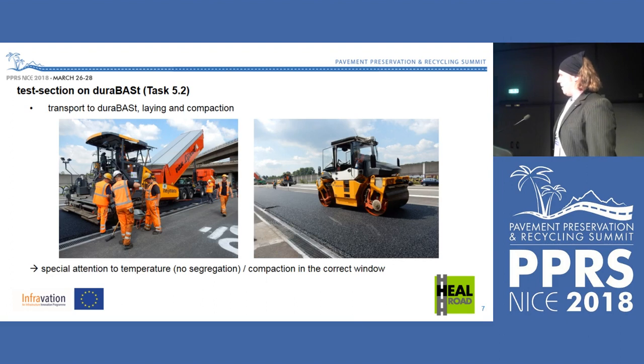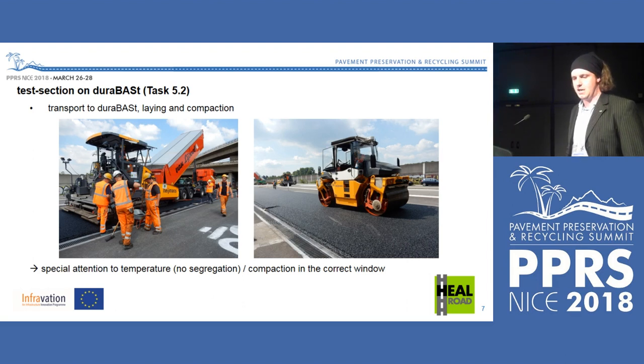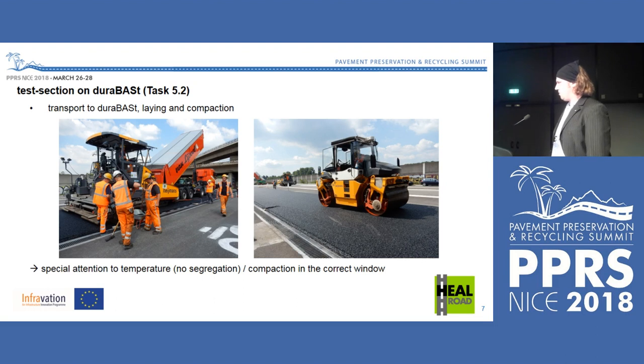The asphalt material was mixed in the Netherlands at the location of Heymans and transported via trucks with isolated trailers to Germany, and we placed it in mid-July. All the temperatures were measured during the transport or at the end of the transport, before we started to pave the surface layer, and during the compaction process, so everything was in a nice window and everything was working fine with standard equipment.